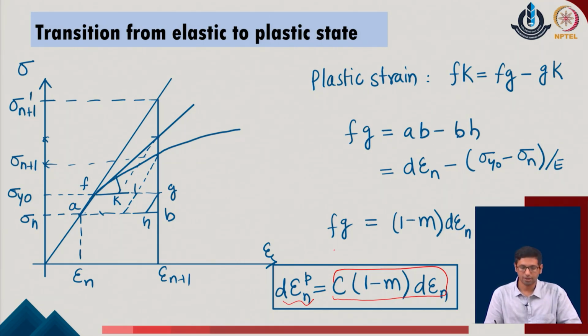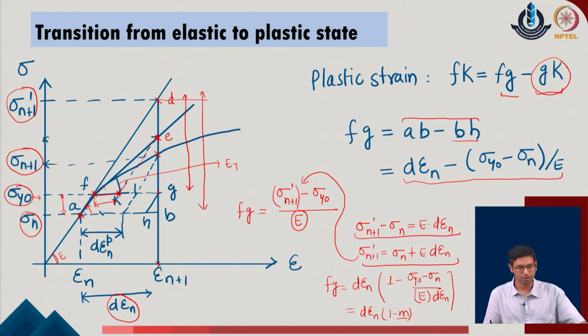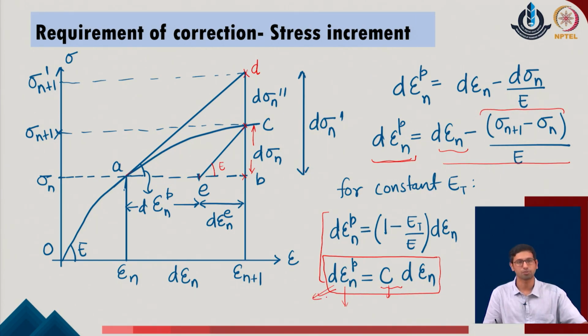So, we are now identifying, of course, this particular relationship is defined in a situation where the elastic modulus beyond the yield is considered to be a constant value, and that is defined by the E t parameter in the given system. So, we realize now that the plastic strain parameter at a point, if it is below the initial yield point of the given system, needs to be evaluated correctly with respect to an expression which is defined over here, and this is a bit different than the actual expression which we calculated previously.